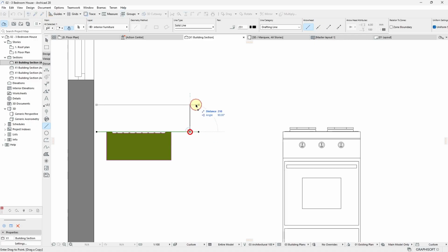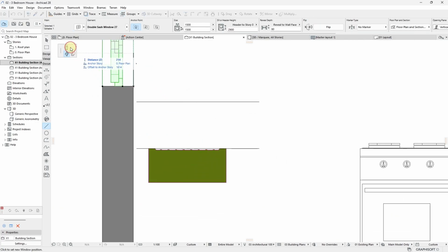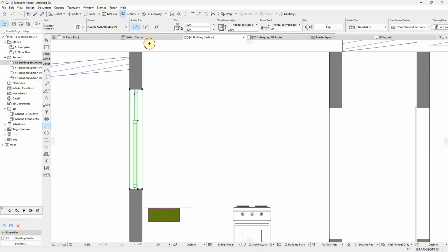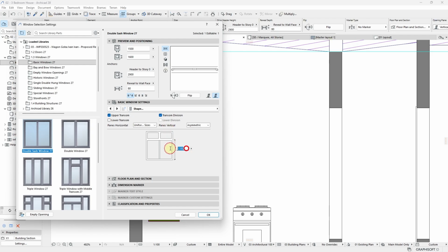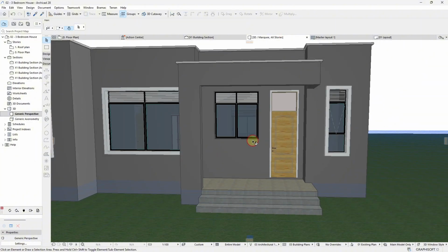And then you always have some space here for backsplash of water. So I'll do this at 300. That means my window can even extend up to here. You don't have a problem with bringing it down here. So at least I have a window of 1.6 by 1.5. We have something like this.